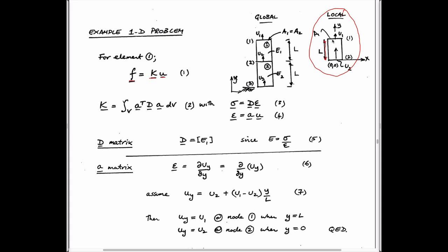It has a cross-sectional area of the element, which is A. And it has, in this case, nodal degrees of freedom, which are only one displacement degree of freedom in the x direction. We don't have horizontal displacements, or in the y direction, I guess, in this case. And we have nodes 1 and 2. So that's our template that we'll use to put on this. We take that template and we make a system which is more than one element. Global node 1, global node 2, global node 3, and those will comprise how we use these templates.